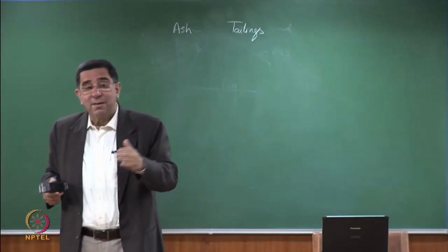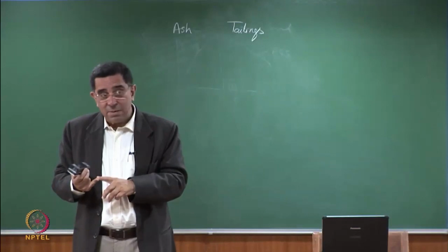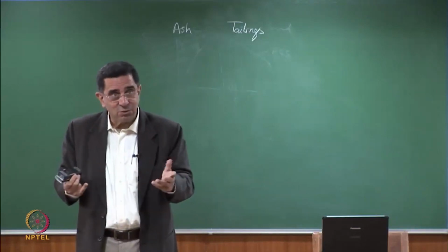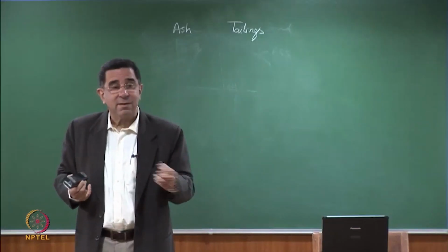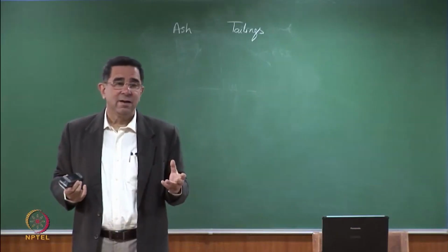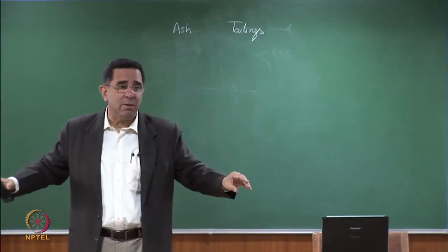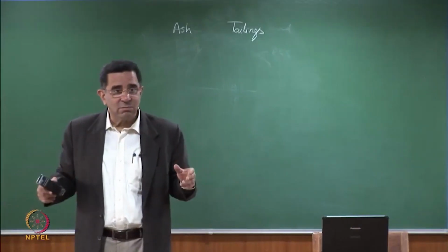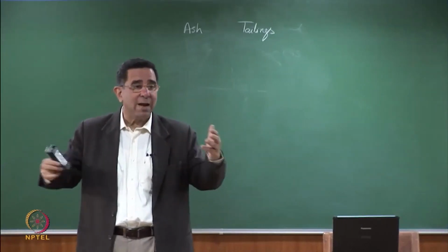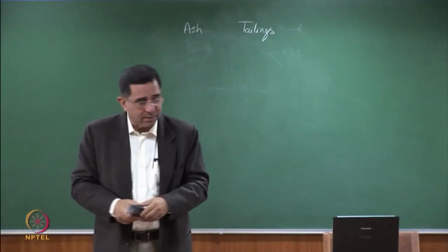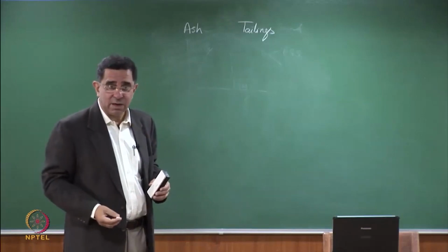Even marble, just pure marble cut dust, chemically has no problems. We are using marble in our houses. What is the problem? Erodibility. Dust and rainwater erosion. So the solution may just be putting a soil cap on it. The solution may be just in the form of putting natural soil and vegetation so that it doesn't become mobile. But we have to recognize that. So there are other types of slurry waste which you will also have to address from time to time.